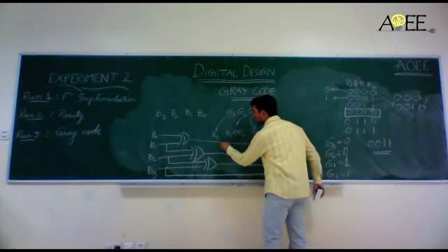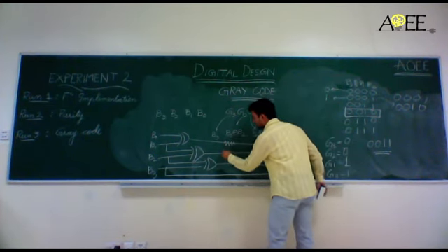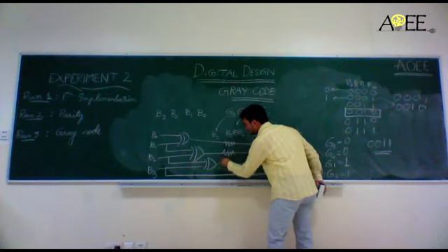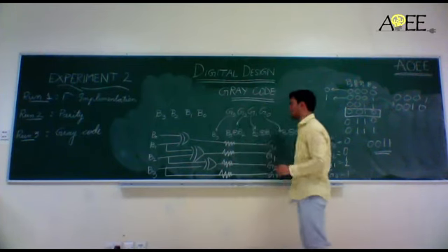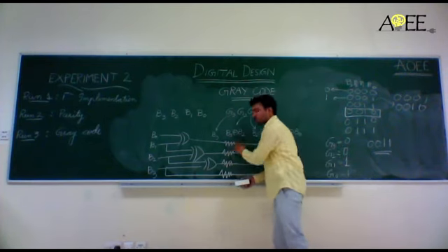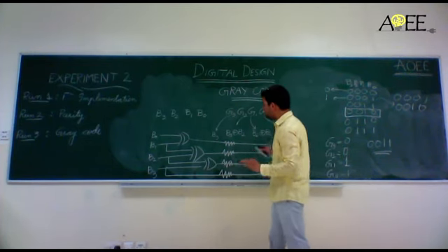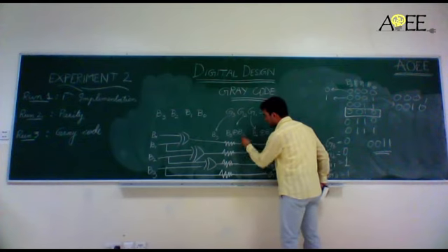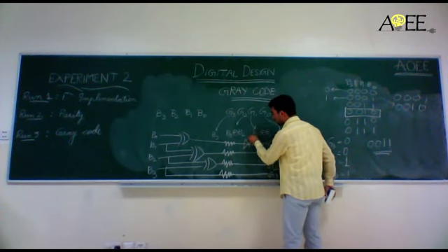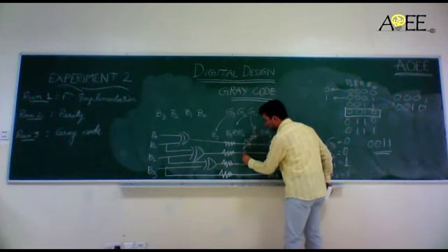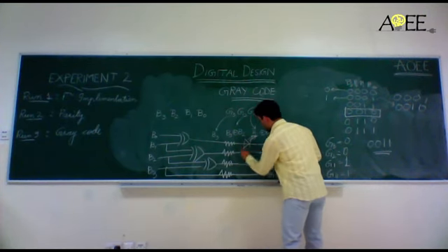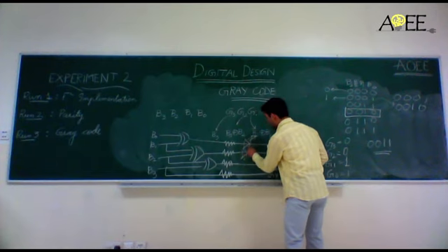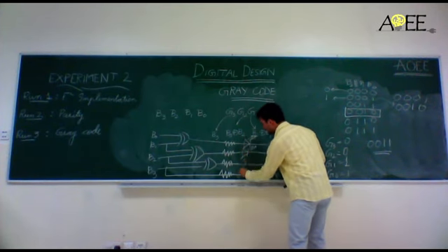And it's important that you have resistors. They are there for the purpose that no gate is left floating. You should have resistors to make the circuit proper, and after that, LEDs have to be connected, which is how it is symbolized. So in a breadboard, this is how the circuit